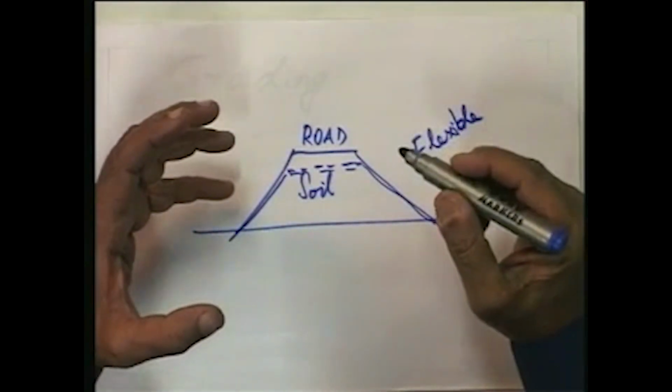And this is what dictates the importance of knowing the rate of settlement, the rate at which settlement will take place. We are generally not very much worried about settlements that take place below a road unless they reach excessive limits, but we are certainly worried not only about the total magnitude of settlement undergone by a building, but also the rate of settlement. Therefore, depending upon the structure, the total settlement is really of course important, but the rate of settlement might also be important in structures where the adjustment is not easy.